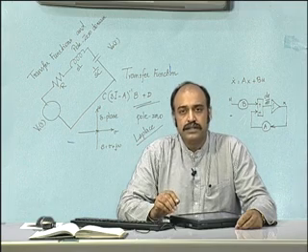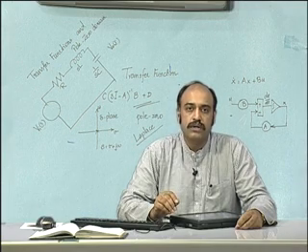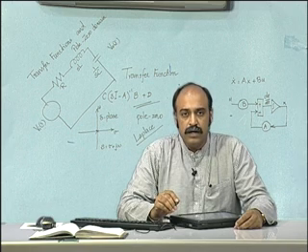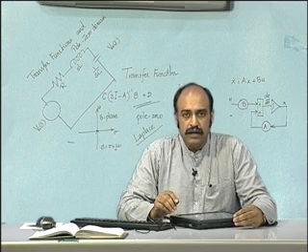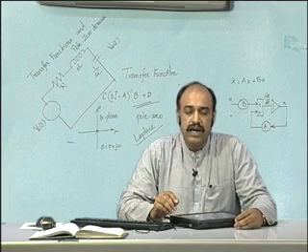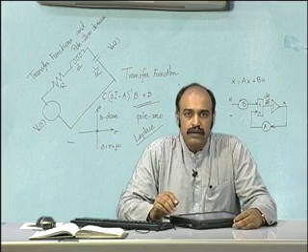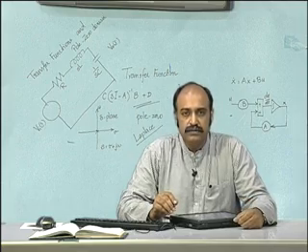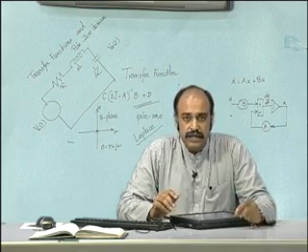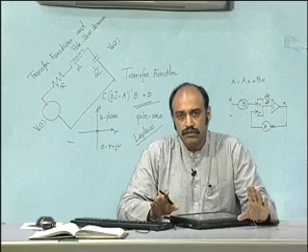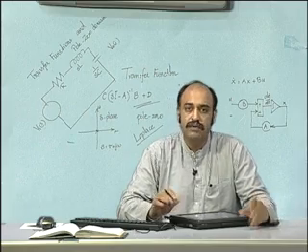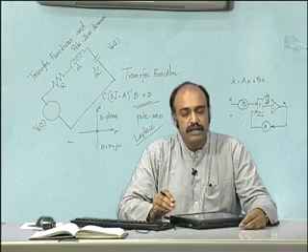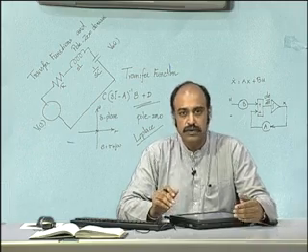In this session, let us have a closer look at the pole zero domain, and a method of modeling called the transfer function modeling. It is again a special case of the state equation. As I told you earlier, the state equation will give you the overall total dynamic behavior of the system. It contains in it the information about the steady state model and also the transfer function model.